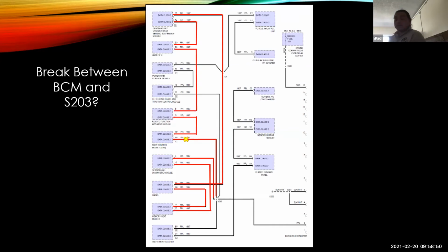Right. I have no problem shipping it as long as the customer owns the decision. It's their decision. I mean, we do that all the time. Do we replace the whole wiring harness, or do we open it up and repair the wire, or do we run a wire down the outside of the harness? Well, that needs to be a customer decision, because what are the odds there's only one damaged wire in the harness? Pretty slim. But we all have customers that don't have the money to fix it right.